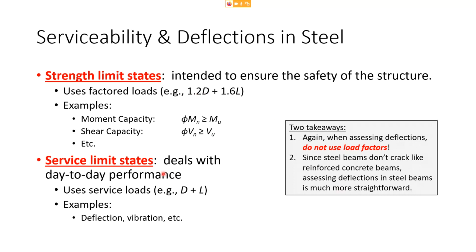However, with service limit states, you use service loads. You do not factor the loads. And the reason why that's relevant is because we're looking at 3 things. We're looking at moment capacity, shear capacity, and deflections. Whenever you're looking at deflections, you do not factor the loads. You just use the raw loads. It's because we're not dealing with structural safety. We're dealing with issues that if you fail a service limit state, it doesn't mean that the building's going to fall down and kill people. It just means that it's not performing the way that you wanted. So you still need to check it, but it's just not as big of a deal.